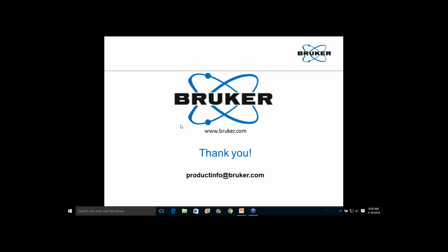Any kind of measurements we do, it is better to report how testing was done, the way it is done. These tests are actually relatively new, hot hardness test using UMT TriboLab, and we need to report the way it is tested, what ball was used, how loading was done, what was measured, and how this hardness was calculated.